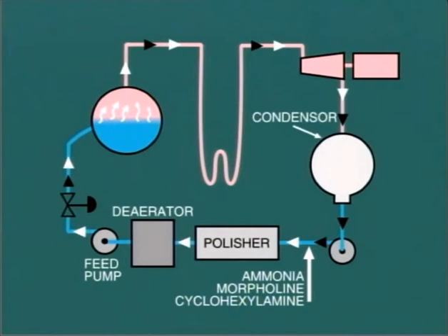This material circulates through the steam and water cycle, with makeup being added continuously. The effect is to raise the pH value of the water to protect against acidic corrosion in both the pipework and the boiler. Clearly, from our discussion here, we can see that boiler water conditioning is often a compromise, and it does require experienced water treatment specialists to establish the procedures for your particular boiler.